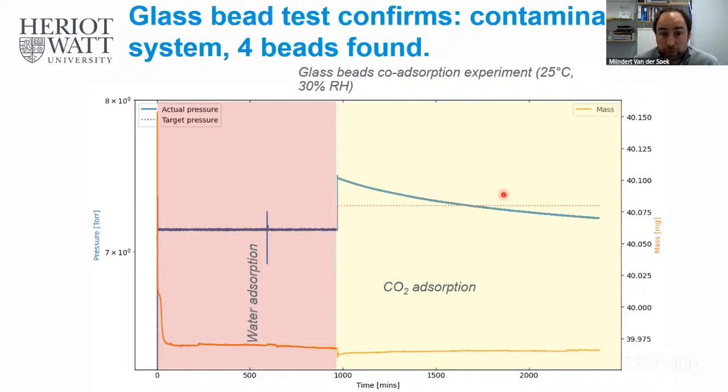And in this case, what happened was that we had contaminants. So we had some adsorbent beads that had spread through the system, and they were stuck on a ledge somewhere, and they were not in the sample pan, so they were not contributing to the mass change, and therefore we had actually adsorption going on while there were no official adsorbents in the sample pan. And these kinds of things, continuously going back and forth, is what makes this very challenging.